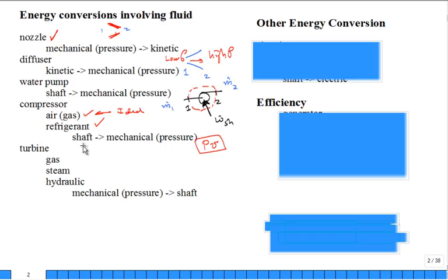You treat it as ideal gas like air, and you can do a pretty good analysis of that. You could have a steam turbine in a power plant. Don't necessarily treat that steam like an ideal gas. Absolutely not. Stay away from it. Treat it using the properties and the steam tables, because the fluid doesn't behave as a true ideal gas as it flows through the steam turbine.